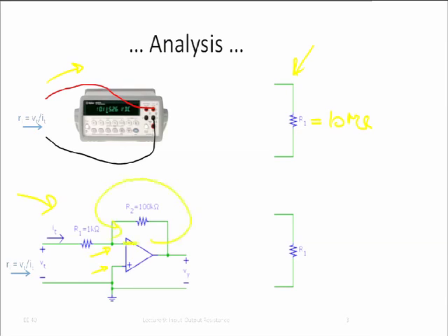Okay, so if here we have a voltage Vt, and here we have a voltage 0, the voltage across the resistor R1, of course, is Vt, and therefore the current flowing through it is Vt over R1, that's It, and the ratio Vt over It then is just equal to R1. So here this actually is equal to R1, which happens to be 1 k ohm here. So really, what we are doing when we are hooking that operational amplifier up to a temperature sensor is we are connecting a 1 k ohm resistor to the temperature sensor.